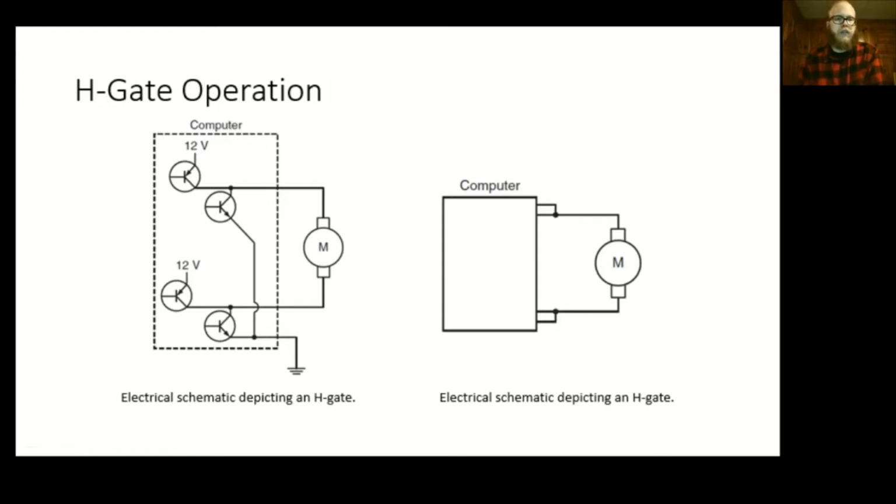And that's what it looks like if we actually saw one wired up in a schematic. But oftentimes, this is all the schematic will show us: don't worry about what's inside the box. Pay no attention to the man behind the curtain. It's all smoke and mirrors. All they want you to do is check: does the window roll up and down? No. I'm going to check to see if it rolls up and down. Right? Verify customer concern. Still doesn't roll up and down. Is this computer getting the input that it needs to know to roll the window up and down? Well, that depends on the circuit.